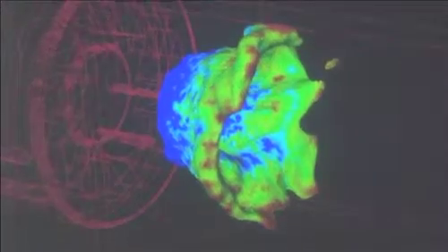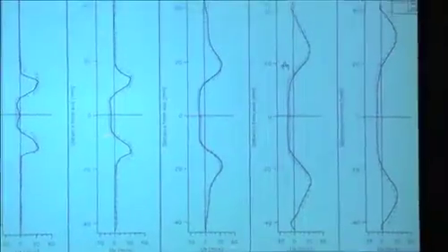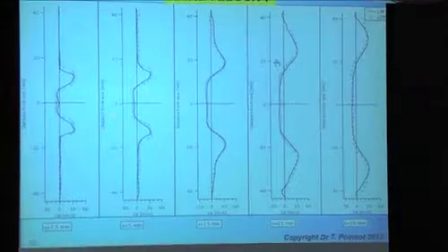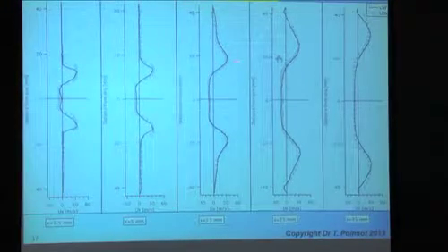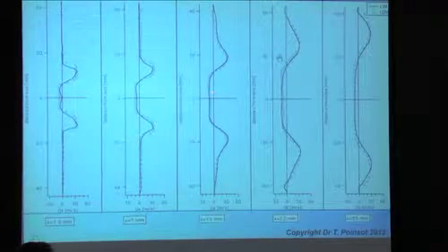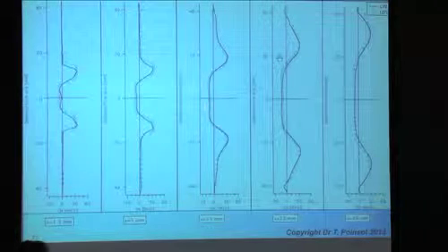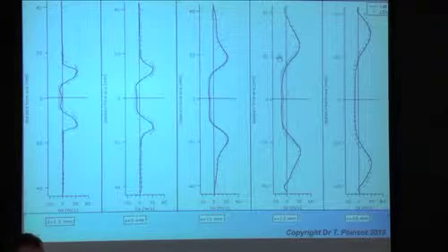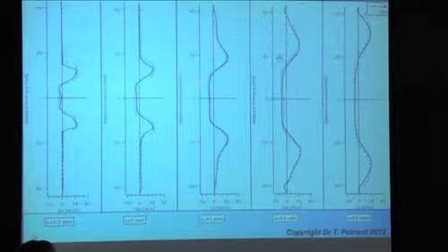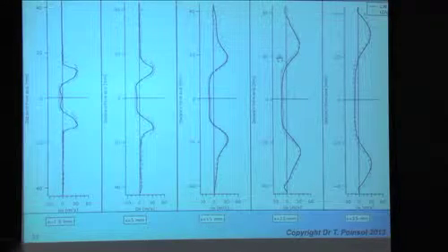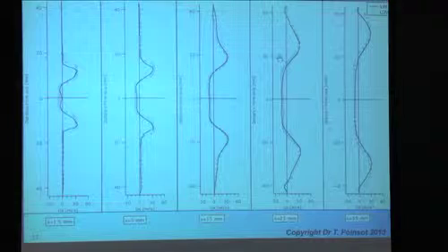So after a few years of doing that, you get used to it. Or you can also use 3D systems to take a look at it. So same thing here for combustion. You can compare the measurements and the LES, and you see it's very good. You see that the profiles are much flatter here, and the recirculation zone is even larger. Look at this recirculation zone here. With a constant velocity, it's taking a big portion of the engine, and this is really the place, all these points here recirculating are really stabilizing the flame. They are there to do that.